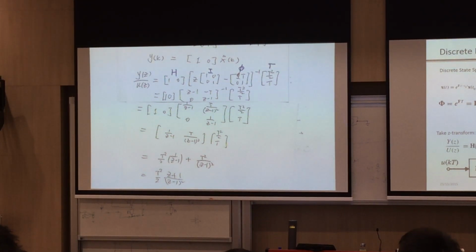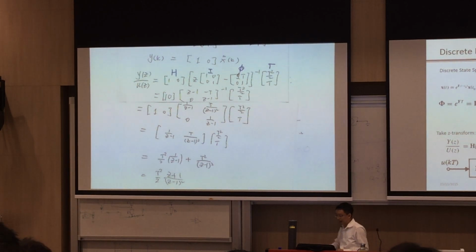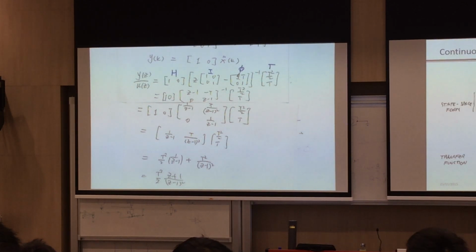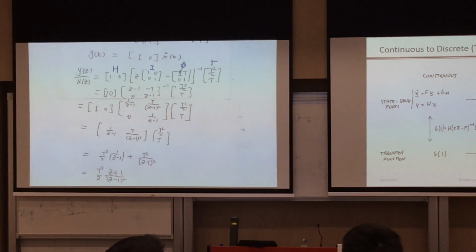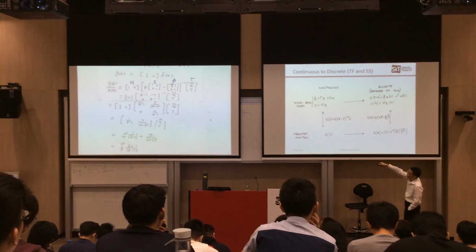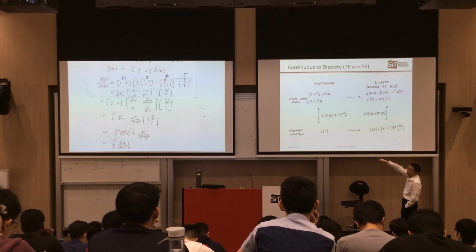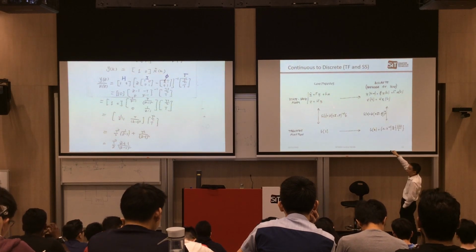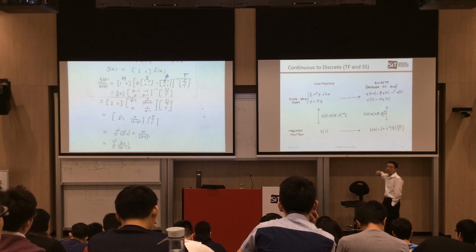If you have done one of the two, the so-called exercise 6, right? Ask you to find out the zero order equivalence of 1 over S, right? And at that time you get this one, right? So basically, you can find your G(s) divided by S, do the Z transform, multiply with 1 minus Z power minus 1. You get this one, right? This is something you have done through your exercise question, exercise 6 or 7. Now, what you can do, you can also do this, convert to the space, digitize the space, then convert to the function. Okay.